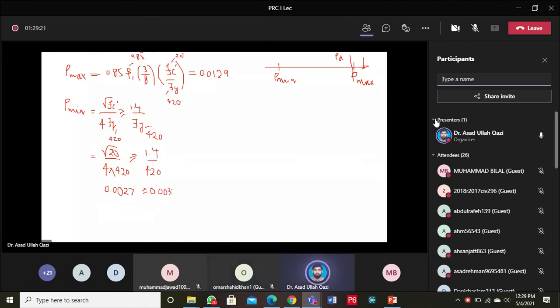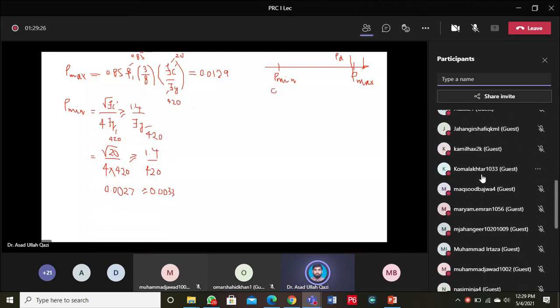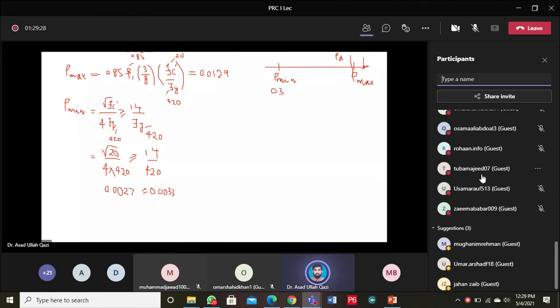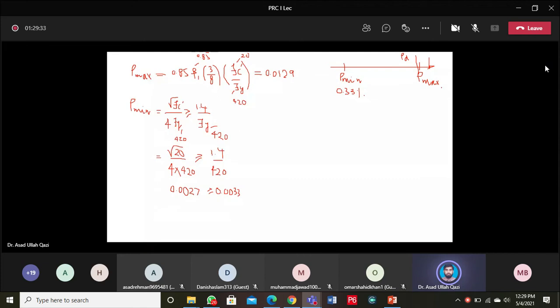Agreed. Right. So it is 0.33%. Rho max is 1.29%, and what we have done is 1.28%. So there is good news that we are successful in designing a rho which is less than rho max, ideal.